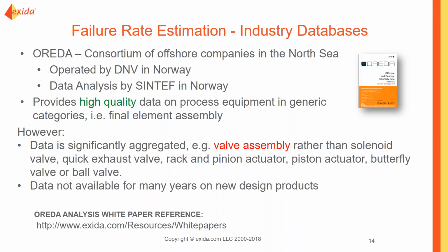The caveat, or the thing that you need to consider when I say you need to learn how to use this information, is the data doesn't go down to the instrument level. And because of that, it actually starts becoming challenging to even meet the requirements of 61511 now. Why? Because you have to show justification, and that justification seems to disappear, because now when they say, hey, what has failed? Show me proof.